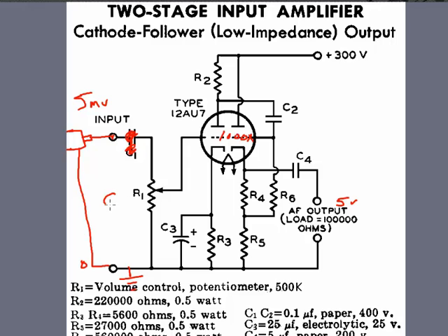And what you're going to do is you're going to grab the knob and turn it left, typically for down, and right for up. And when you're doing that, it's a potentiometer I showed you in the last class. And really all you're doing is sliding this little lever up or down, right? And if you remember what we just taught a minute ago, as you slide that thing up and down, what you're really doing is varying the amount of resistance on the top side of this and the bottom side of this.